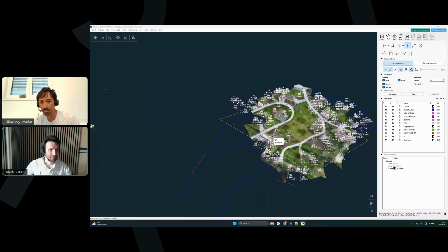But let's see. I tried to combine the waypoint flight close to the facade photo with the gimbal angle at 30 degrees, but for some reason the software did not manage to combine it with the initial double grid flight of 90 degrees. Are there any special settings for this flight? You mainly covered this one, but another factor also depends on the building texture.